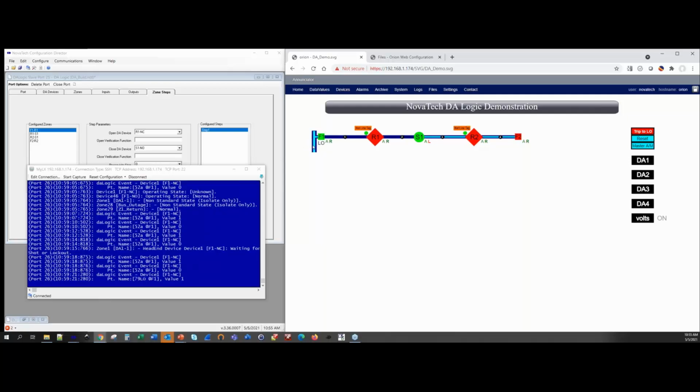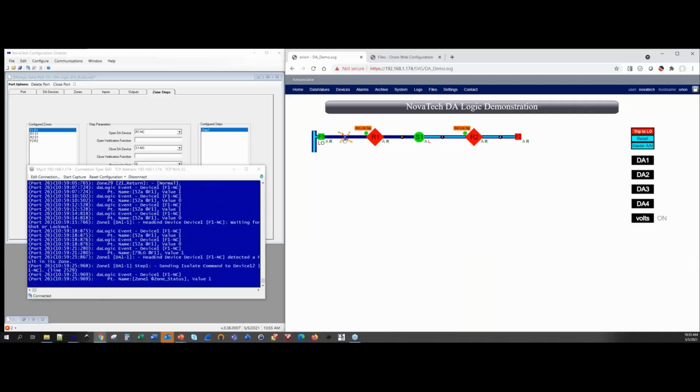Okay, we reached lockout, so now we have a fault indicator. We have the lockout indicator. It identified the fault as being here. It's going to send and isolate to recloser 1. This device, switch 1, is still in local, so this recloser 1 goes into limited mode. It's not in an abnormal state. It's because it is in auto.